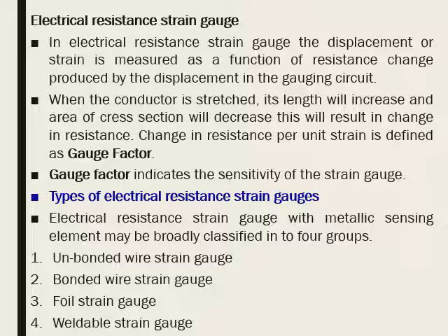The strain gauge serves as an element of a high frequency generator, and the change in the strain gauge capacitance results in a change of the generator frequency. So, from the frequency change of the generator, it is easy to judge the magnitude of the deformation in the place where the gauge is fixed.